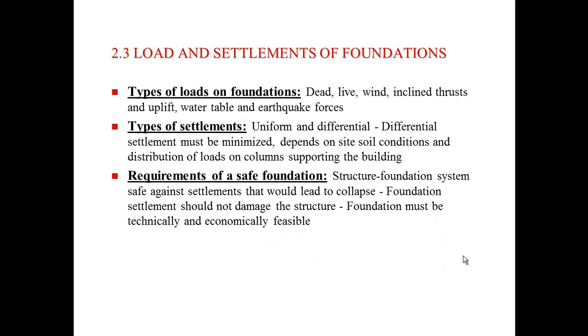Types of loads on foundations. We have dead loads. Dead load is just the weight of the building itself. Live loads could be movable furniture, people, anything that can change within the building, and there are maximum live loads for certain floor levels. Wind loading, inclined thrusts, uplift, water table forces, and earthquake forces or seismic forces.